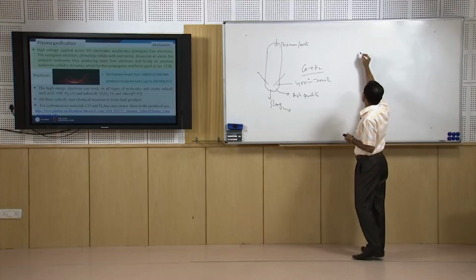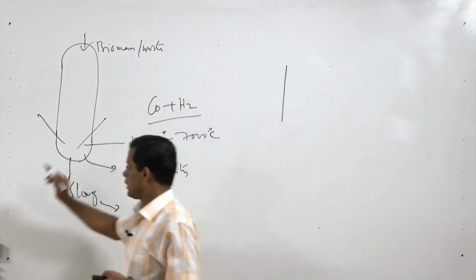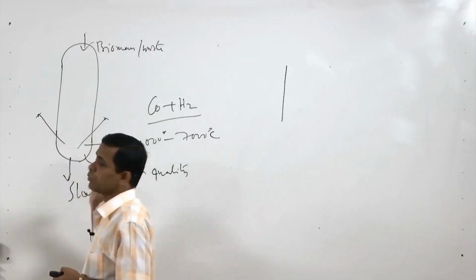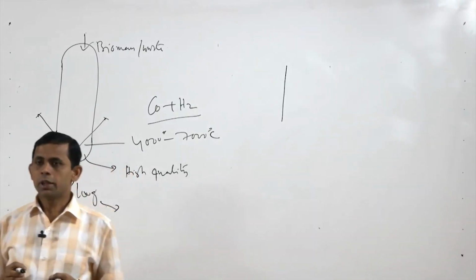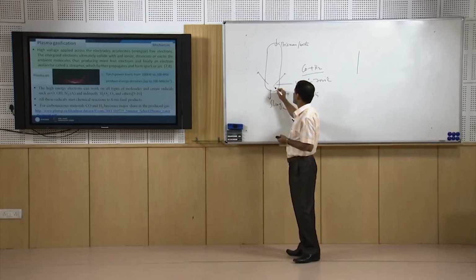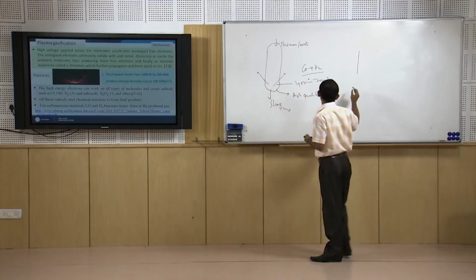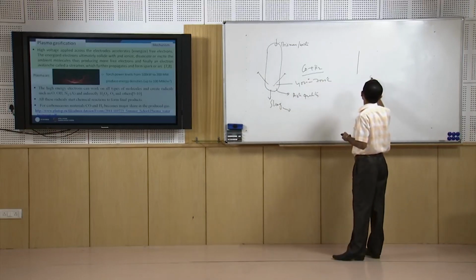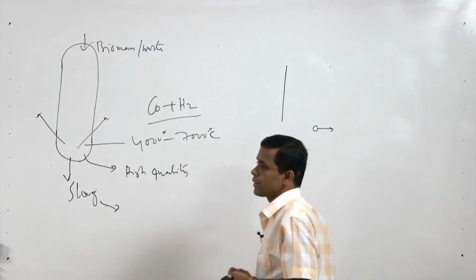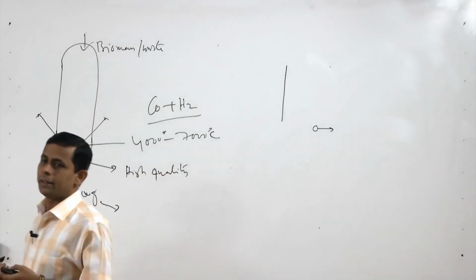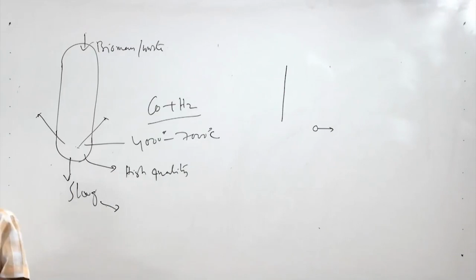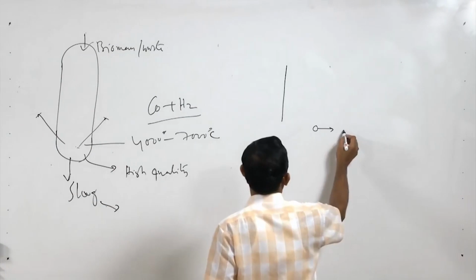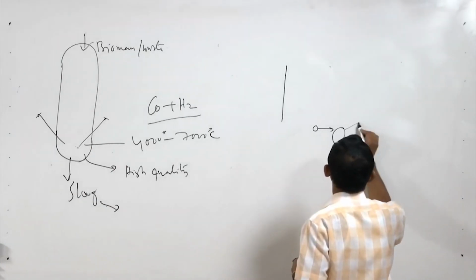We need to provide high temperature by the application of high voltage across two electrodes, and when these two electrodes are under high voltage, the velocity of the electrons generated here is accelerated. So, these free electrons will collide with nearby molecules, disintegrate them and generate further electrons.